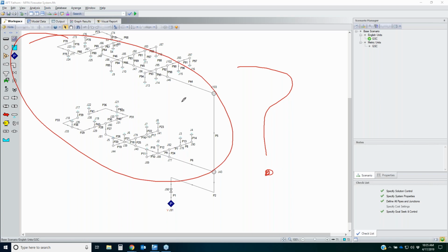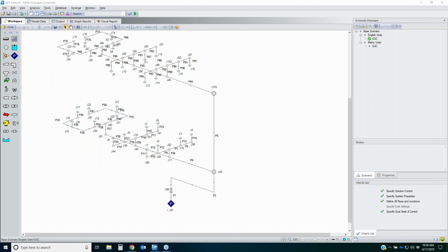It depends on the hydraulics of each individual flow path to every single spray nozzle in the system. So this is a case where you cannot just say, I want the minimum to be based upon this guy right here, because that very well may not be the furthest away. It could be a situation where maybe this spray nozzle is actually the furthest. You have no way of knowing, and this is where it's incredibly useful to allow the goal seeking control module to figure it out for you.